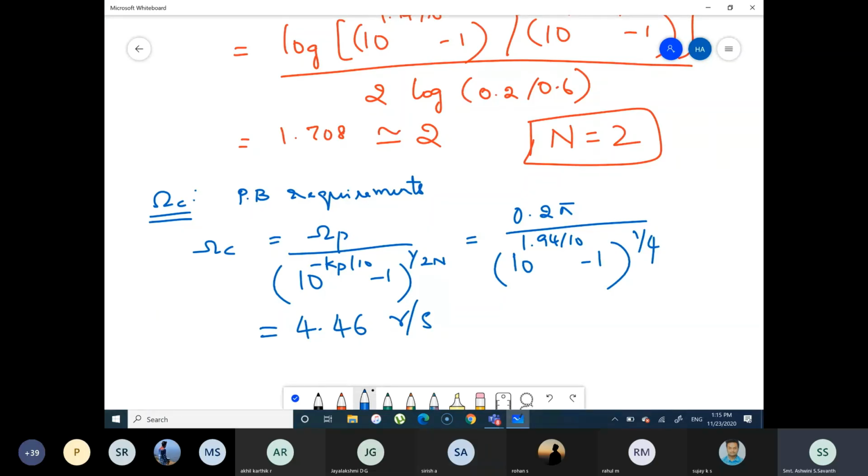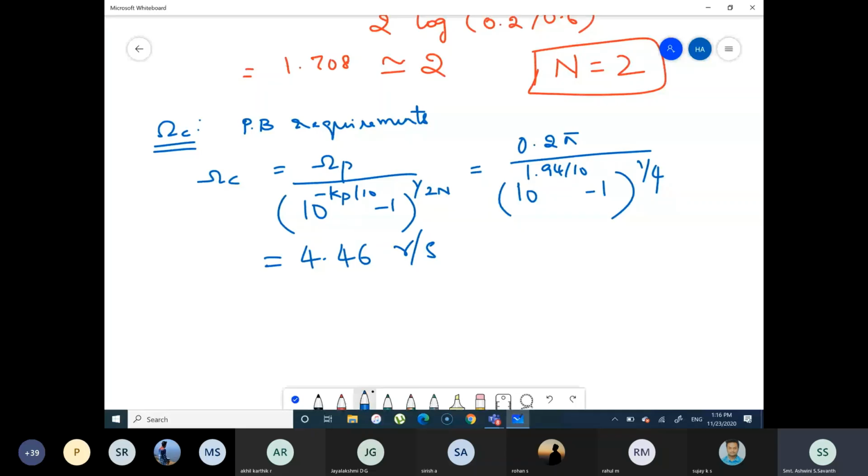Okay, next, we can write down the transfer function of the normalized filter. So it's a second order filter. Therefore, what is the Butterworth polynomial for second order? Here I'm writing it directly, but in the exam you'll have to derive this Butterworth polynomial. At least write the expression for the poles of the transfer function, what is the angle, etc., what you're going to substitute. Consider the left half poles. Whatever we discussed previously, you will have to do it according to that. Here I'm just writing it directly because we have already derived the second order Butterworth polynomial.